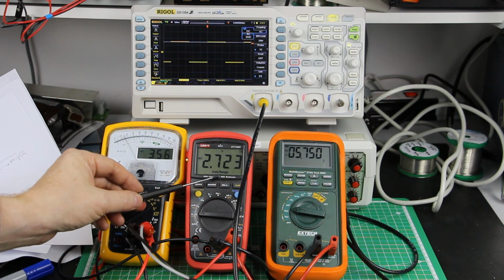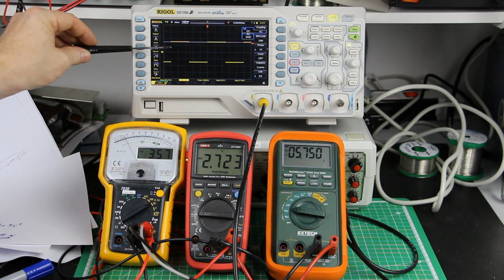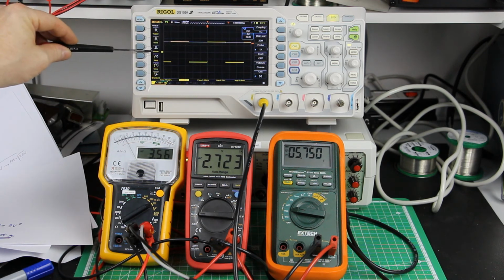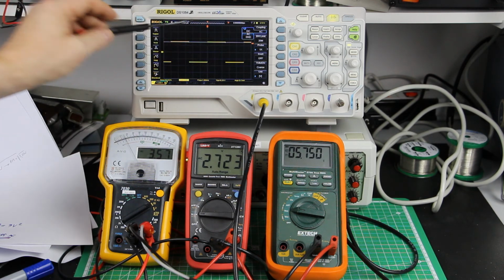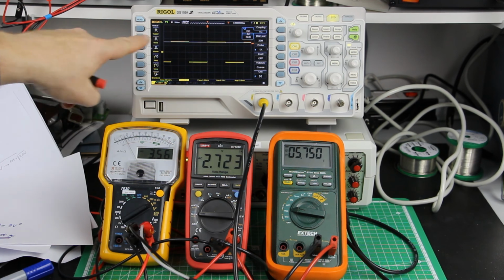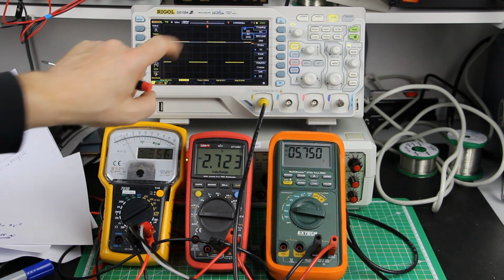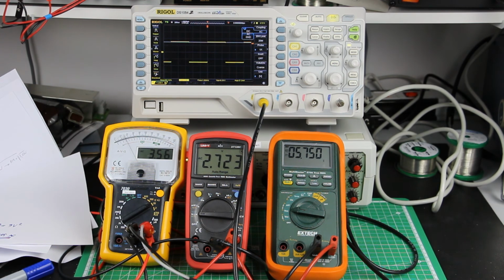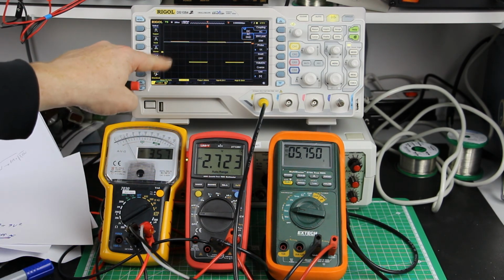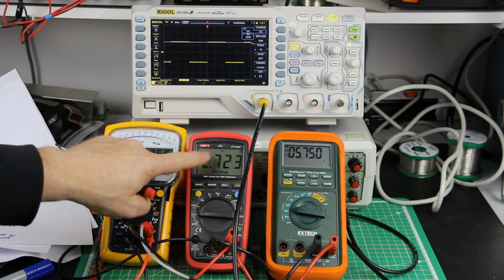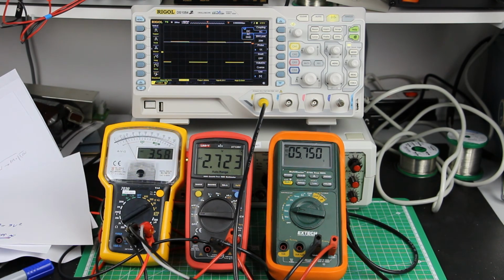It does true RMS only for signals that are symmetrical to the horizontal axis. As soon as you have a DC offset, it gives you a wrong value, and even here, where it should give you the correct value with a symmetrical signal, it's 10% out of range.